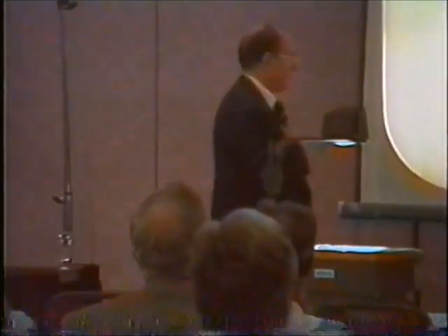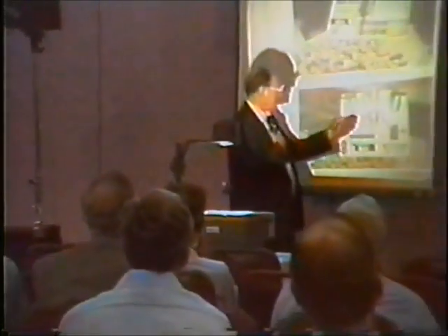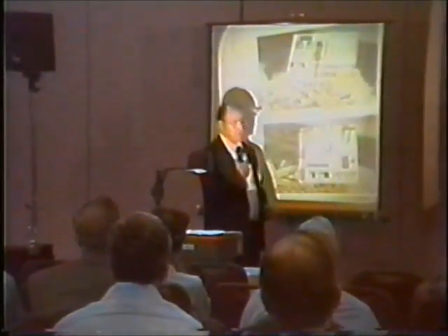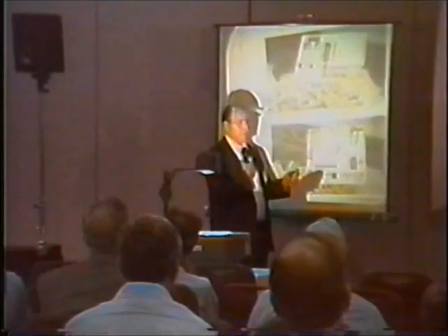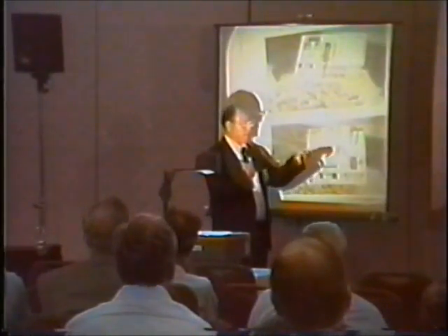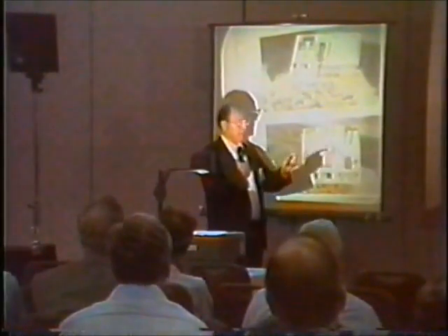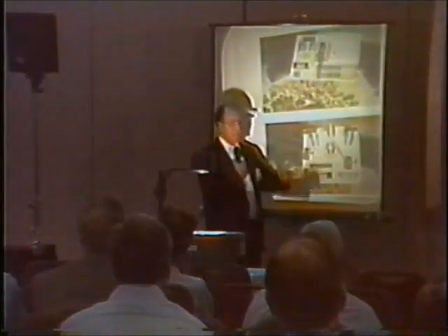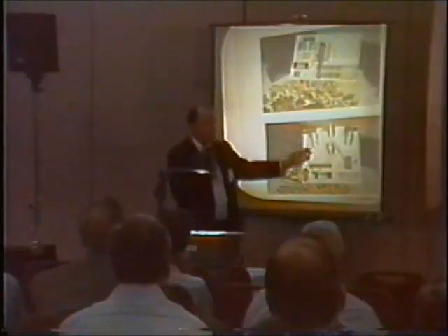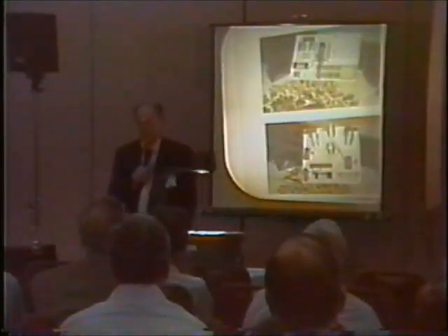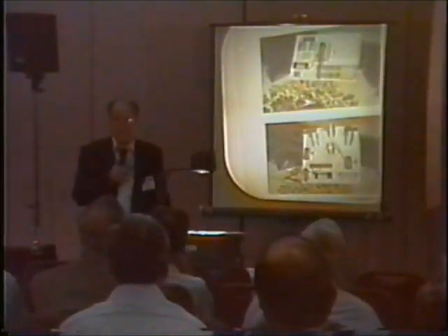And how you know when they're tuned or actually functioning: there's a little neon light with one leg having a resistor, about a 47,000 ohm resistor, on one leg of the wire on this neon bulb, and then there's another leg that just sticks out like an antenna. When this thing is functioning properly, that bulb lights up. So you know immediately when it's working.